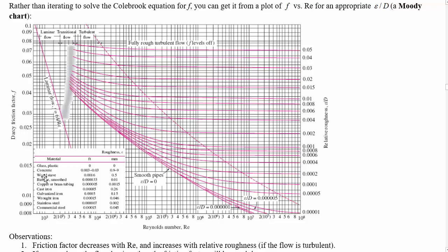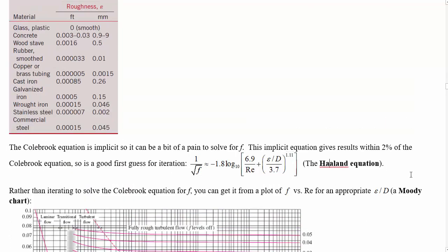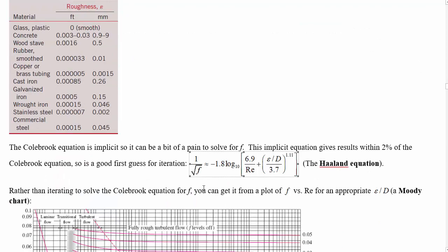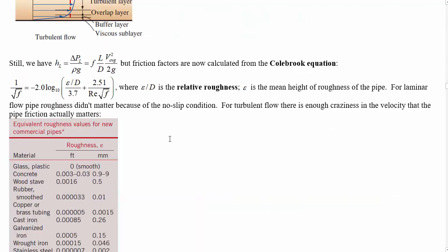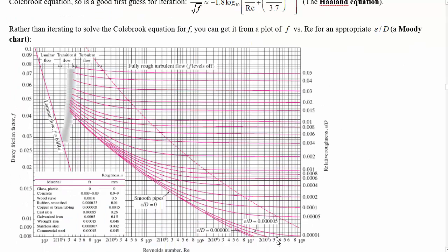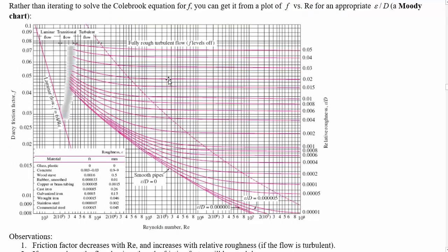It's probably not going to be extremely accurate for you either while reading off the chart, but once you get good at it anyway, it can be faster than substituting things into the Haaland equation, and almost as accurate as this, nominally as accurate as the full Colebrook equation, if your ability to read off the chart is flawless. The best part about the Moody chart, I think, is not really the ability that it gives you to calculate